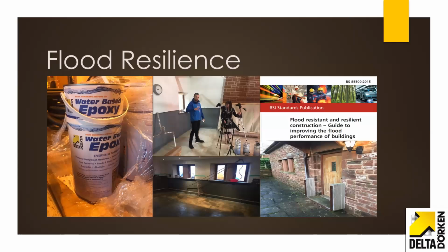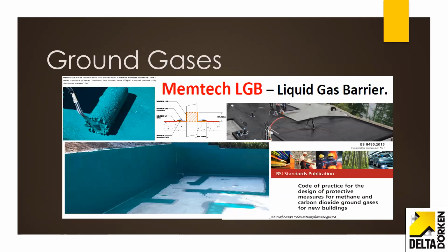We look at flood resilience. We'll see that flood resilience has an impact on below ground structures and waterproofing design in terms of climate change, surface water flooding, and what threats that poses to the integrity of a basement or a building. So these are all related disciplines. Brownfield gases. I was just saying to Rosemary before we started that we deal with basements in brownfield sites or otherwise contaminated land, or land that is at risk of latent fuel spills, for example, or methane or CO2, you know, from industrial processes and whatnot.